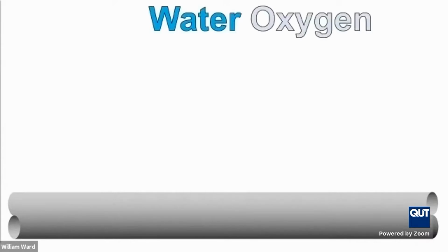Now, first option is you think, oh, we could just put some sort of sensor in for pH. I'm not currently aware of any direct pH sensor for use in concrete structures. So let's take that one off the table and let's start to be a little more clever. Well, we said that we need to have water, we need to have oxygen at the level of the reinforcing steel. We can't directly measure these parameters, though we can use something like a relative humidity sensor for moisture,